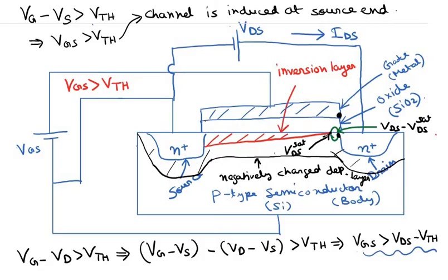Increasing VDS increases the electric field, and we need a thicker exposed depletion region, that is, a thicker region where the channel has ceased to exist, to hold this voltage VDS set.